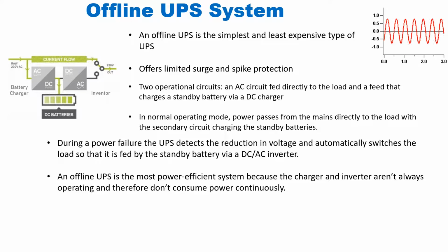The last point that I would like to make here is the reliability. These days the technology has improved, and the circuits and the chips that are used in these offline UPSs have improved from what they used to be. But the inverter is only operational when the mains supply fails. Therefore, the only test for this type of UPS is when there's actually a power outage.